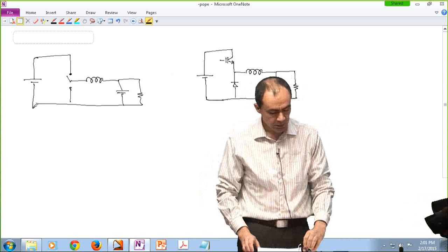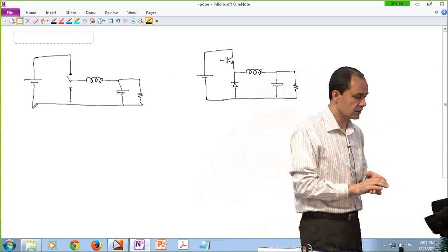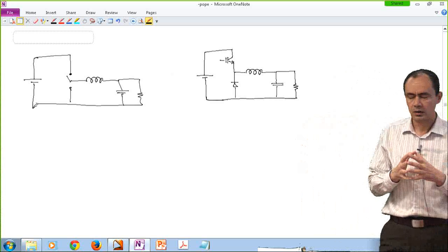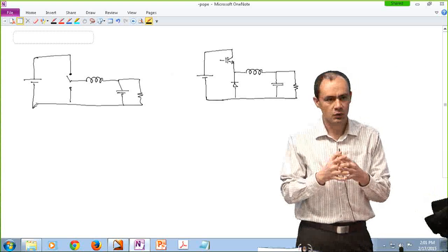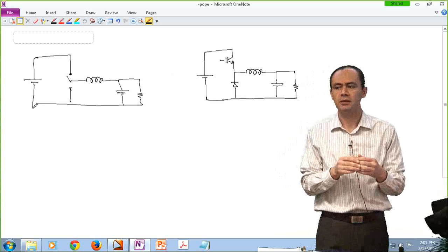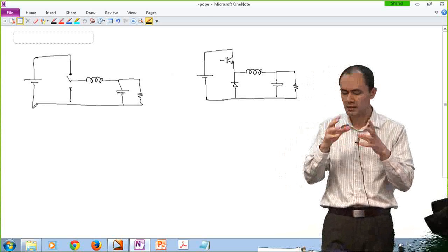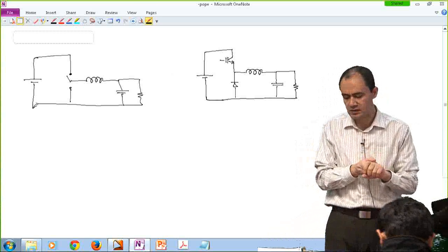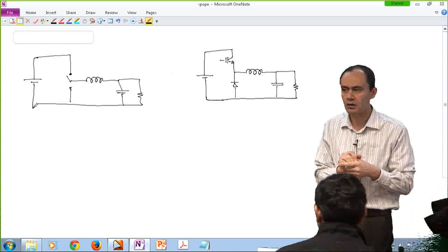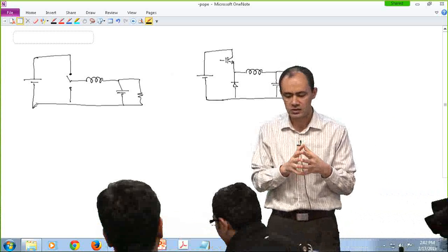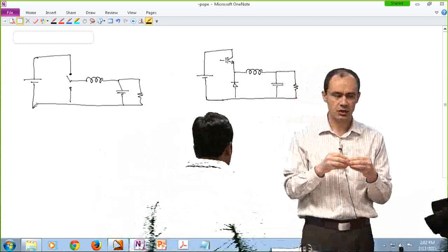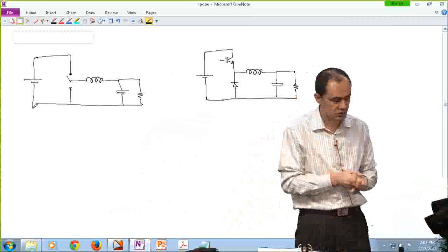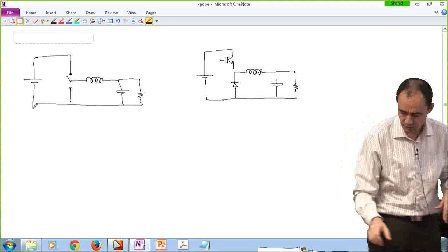Now, as we have seen in the paper that we studied I think last week, in power electronic converters, most of the time switches appear in pairs and they actually form a single pole double throw switch. So one approach would be, instead of trying to realize each one of these switches individually, we can identify the pairs and directly realize the pair. So that's what I'm going to be talking about today.